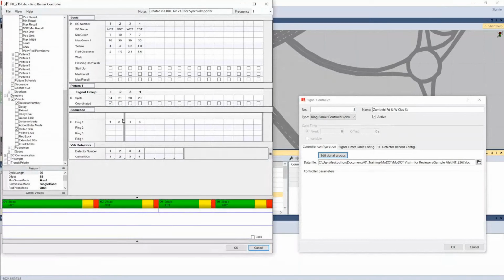So if you're doing a lot of signal controller review, this could really speed up the process, right? Because you're probably going to have the same 10 or 15 parameters that you're going to look at in 90% of your intersections. And so having a predefined layout file, a settings file, will really help speed up that process, so you're not spending time clicking on the individual parameters every single time.